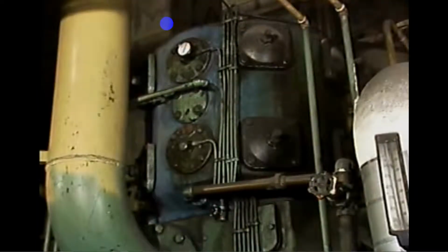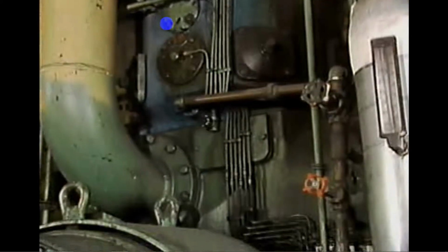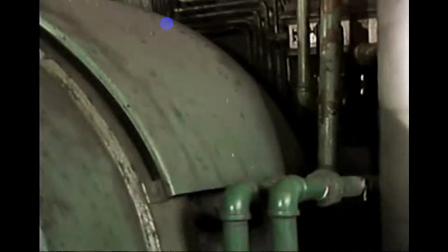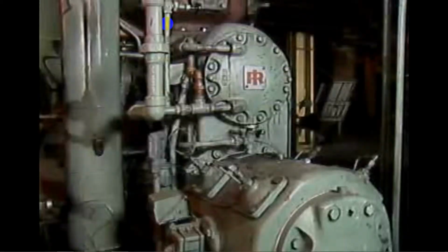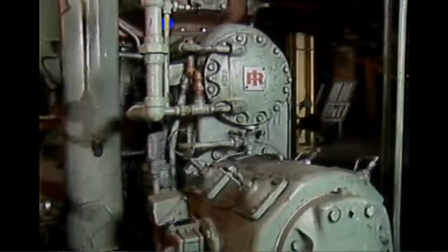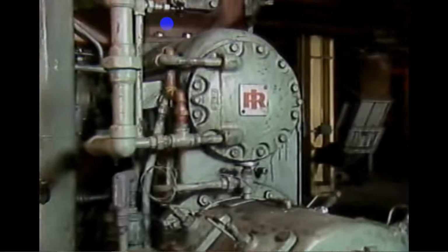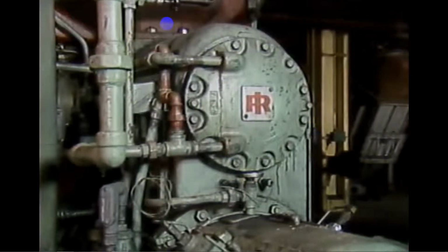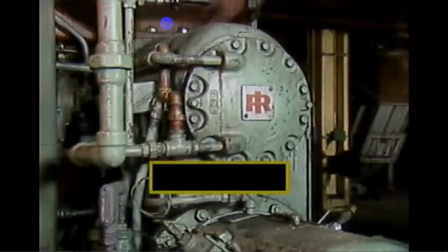Water cooling can be accomplished in two ways. One way is to use jackets. A jacket is a chamber that surrounds the compressor. Water is circulated through the jacket to cool both the compressor and the gas inside it. The other method of water cooling cools just the compressed gas. This method involves one or more shell and tube heat exchangers. Depending on their location, these heat exchangers are classified as either intercoolers or aftercoolers.